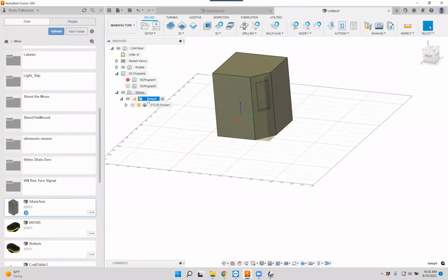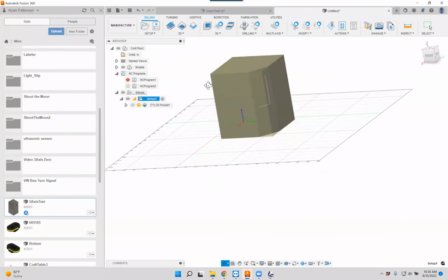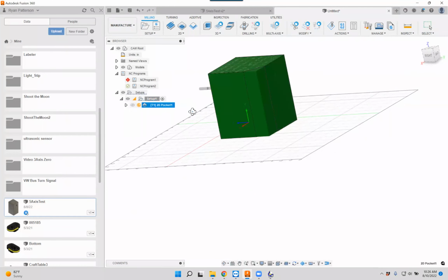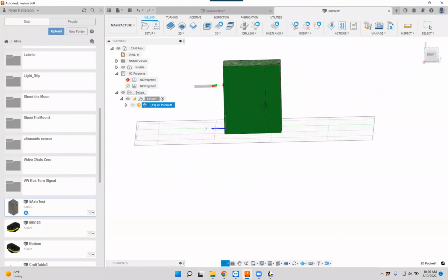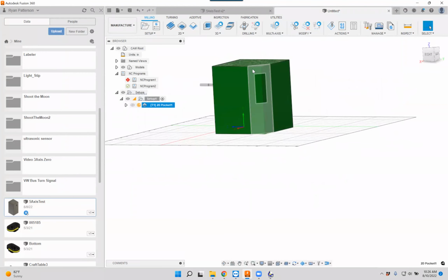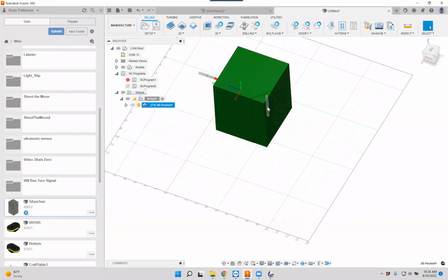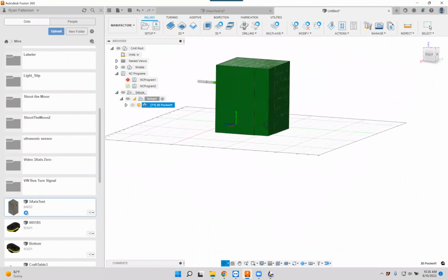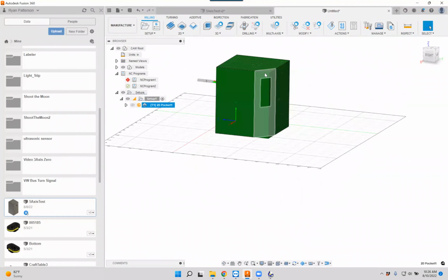And our setup is already completed. So we don't have to go through the setup process again because it is already there. Our toolpath for the circle is still listed there. But now we're in a case where we have some material that we would possibly need to remove first before we could cut out this. So we are going to do two operations here. One that is going to face off the corner of our cube or our material. Then we will set up another operation to pocket into the rectangle that we just drew.